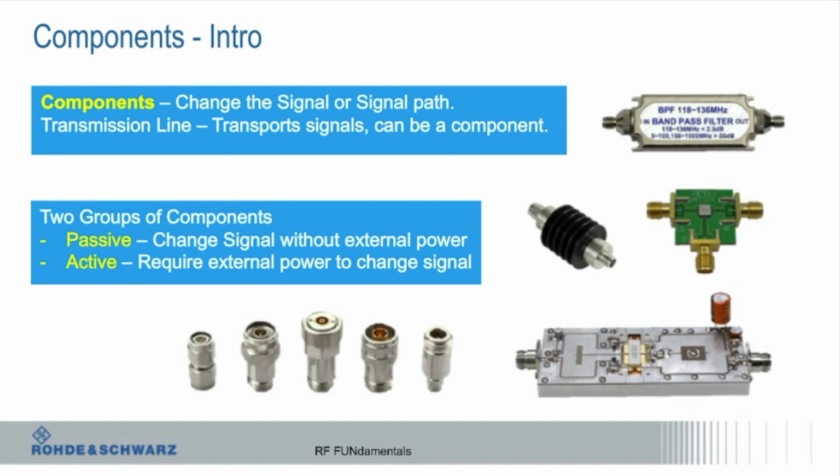So attenuators, filters, mixers usually. There are active mixers. What else? Baluns, all kinds of crazy stuff. And then active, more often than not, is an amplifier. It could be a series of things. In the end, most people are designing a transmitter or receiver or both, a transceiver. If you're designing a transceiver, there's all this stuff in there, so we'll just call that an active device.